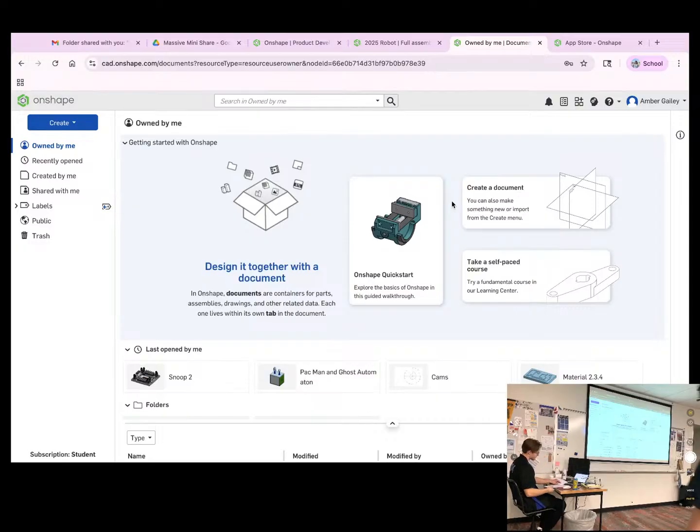The other thing about pneumatics is treat everything as sacred. Don't paint the tanks, don't put stickers on them, don't modify the solenoids. Everything has to work as it was. And the final thing I want to do to wrap up is open it up for questions and answers. Hopefully you picked up on this through my talk this morning.